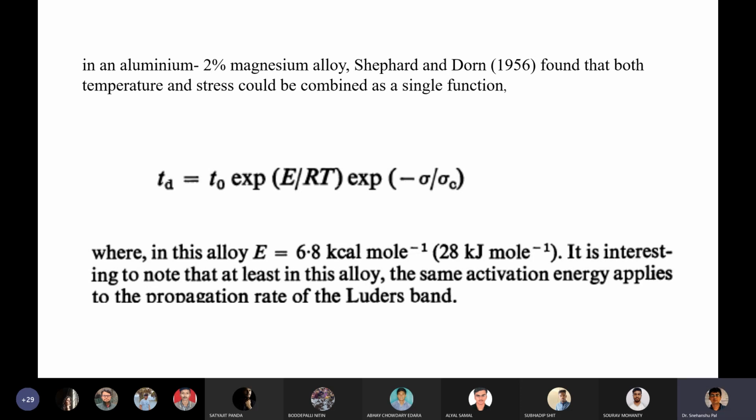So the moral of the story, the takeaway, is that whenever you want to know the yield point phenomena, first you have to understand that it is an inhomogeneous deformation. It is not at all a homogeneous deformation. So when it is not a homogeneous deformation, in a certain Lüders band region or stress strain region, you can see the fluctuation of stress in a particular strain region, and that can be marked as epsilon capital A, lower yield stress region.